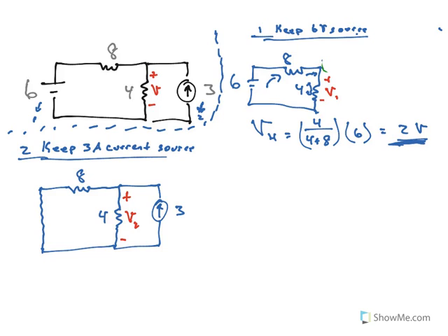All right, so now let's look at this circuit. The 8 and the 4 ohm resistors, they're in parallel with each other because they share this node and this node in common. And all of this is just wire on the left side here. So they're in parallel, and they're in parallel with a current source.